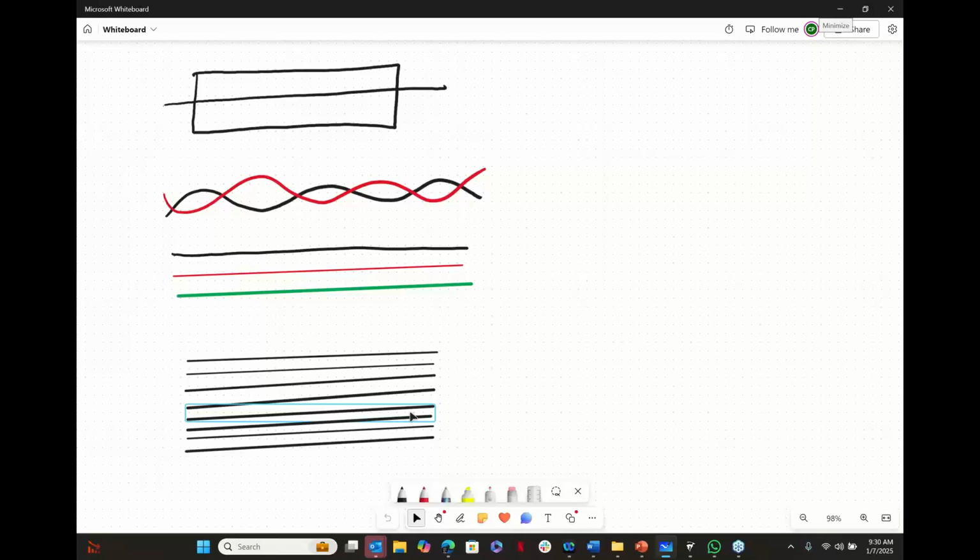But as a for instance, if I look at my coaxial cable right here, and if I pinch it, well, at that point, the outer conductor is closer to the center conductor. Impedance mismatch, TDR sees that rather simply, right? On my next example of twisted pair, if you have one side open, well, that's an impedance mismatch, right? If the cable is completely cut, well, that's the easiest thing in the world for any TDR to see. If your cable is completely crushed, that's also the easiest thing in the world for any TDR to see. If you get water in the cable, get this.